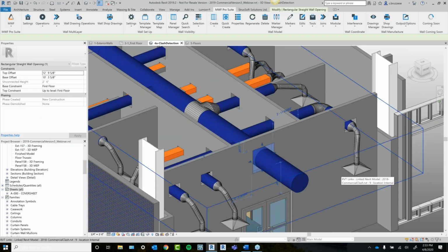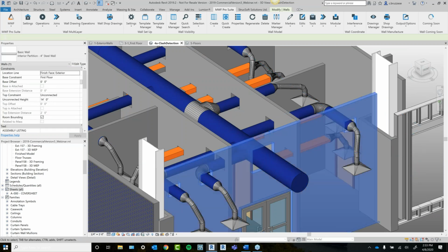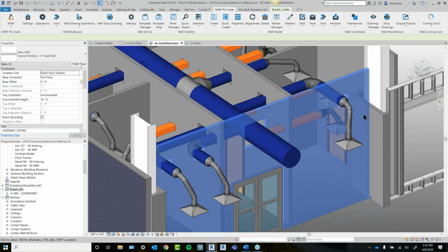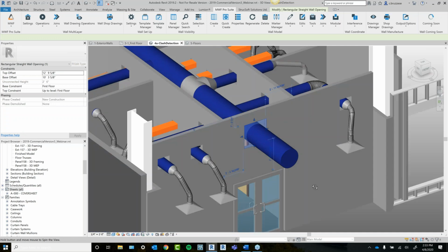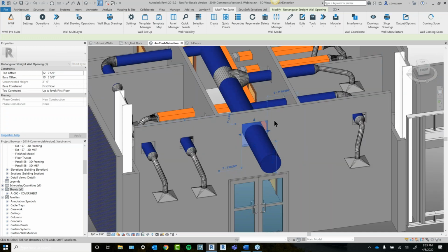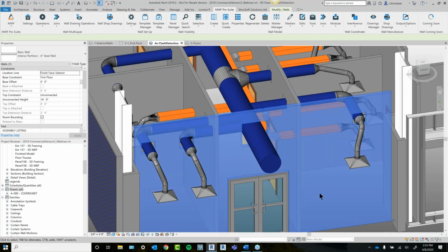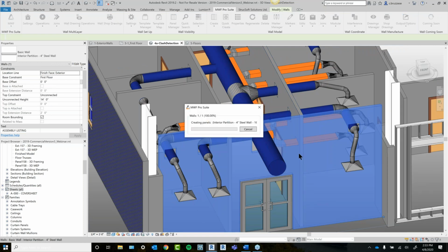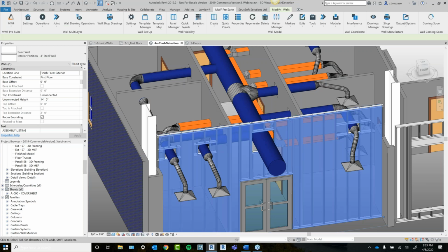I've got everything framed out, or everything punched out, I should say, with the Revit opening. The tolerances are also included to size that opening. And from here, I can go ahead and hit create, and it'll frame out this wall like any other panel.